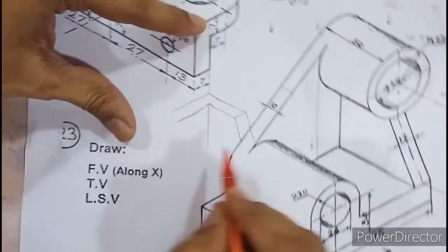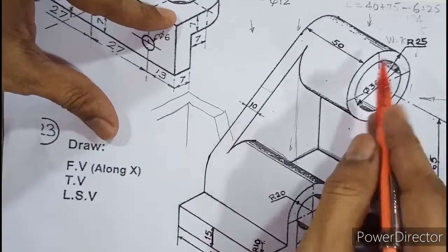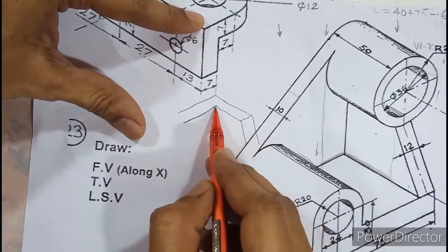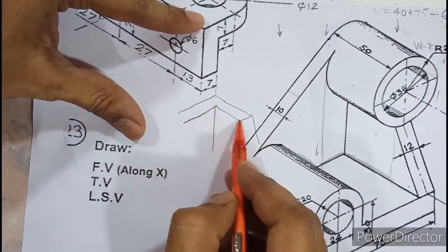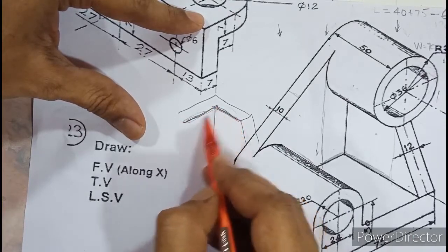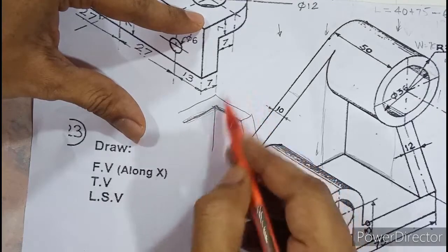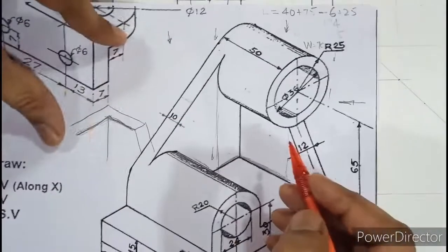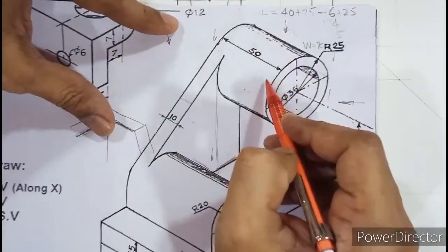Yeah, so that is how the rib looks. If the cylinder is removed, then the rib would be seen like this, L shape. This edge and this edge, both these edges you cannot make out from the top view because there is a cylinder which is overlapping. Okay, so for the last time, observe thoroughly from the top view.